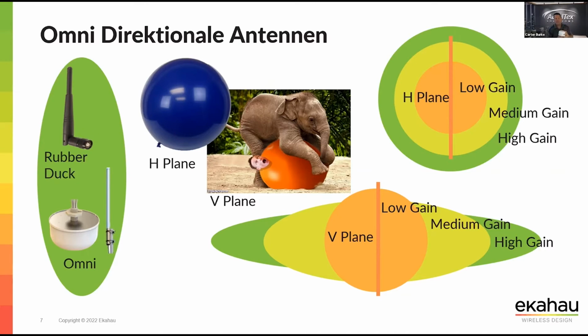So what does that mean? In some applications, you may want to cover, let's say, a parking lot. This is a great antenna for that, as an example. It's going to cover fairly far, but it's going to be squashed down and not as broad a pattern because it's a higher gain. It's designed to cover a large area, like, again, maybe a parking lot. So the thing to always remember is, as the gain gets higher, think of it getting flatter.